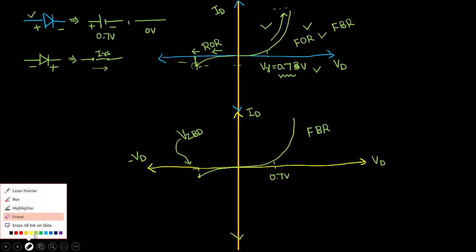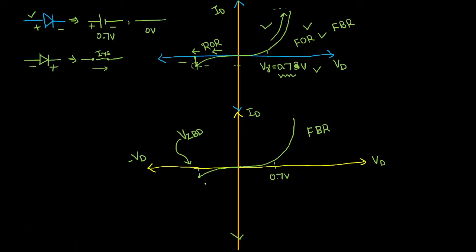Once you enter into that region, what happens, sir? The diode will explode, right? No. In a normal diode, this is where the diode would get damaged. In a Zener diode, the diode will start functioning. It starts carrying an enormous amount of current at the Zener breakdown voltage.